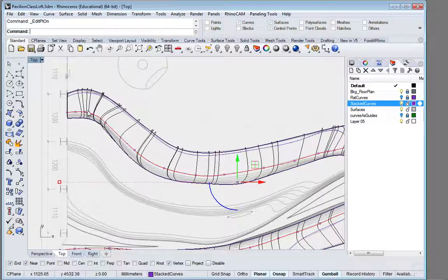Now, each of these lines that you're seeing also has to do with what they call the definition, or think about it as the resolution of the surface. So we can define it. The fewer U and V coordinates we have, the lower the resolution of the surface, so the more approximated it is. So the more of these lines you see, generally, the higher the resolution of the surface. Okay, and you can go back and adjust that.